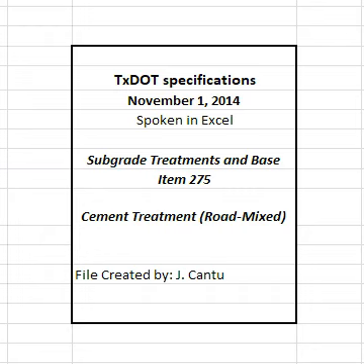3.1 Cement storage facility. Store cement in closed, weatherproof containers. 3.2 Cement slurry equipment. Use slurry tanks equipped with agitation devices to slurry cement on the project or other approved location. The engineer may approve other slurrying methods. Provide a pump for agitating the slurry when the distributor truck is not equipped with an agitator. Equip the distributor truck with an approved sampling device.